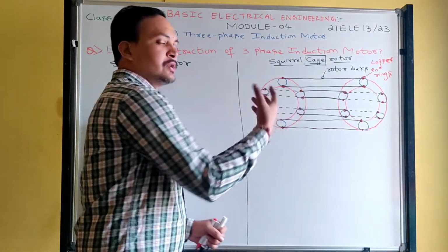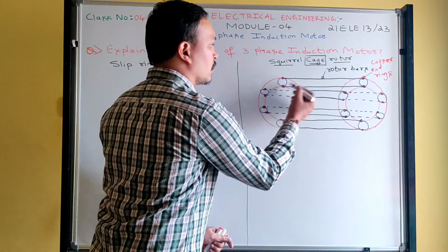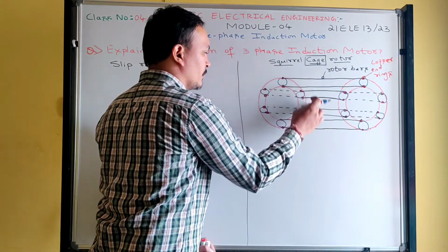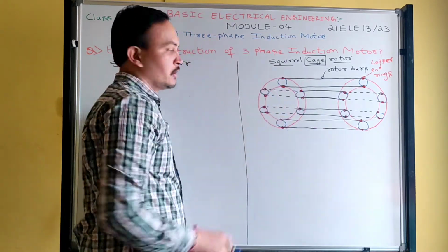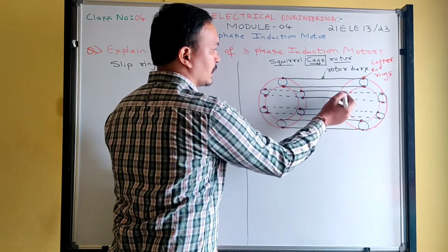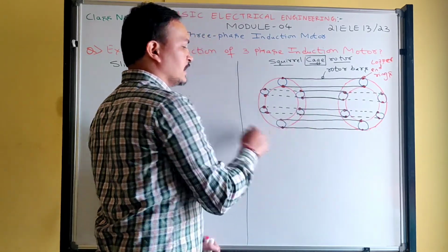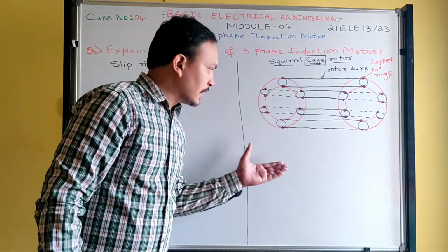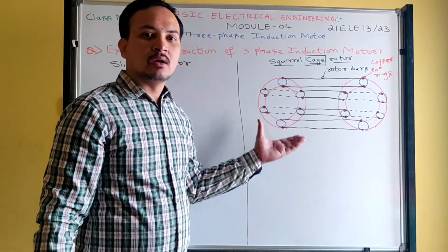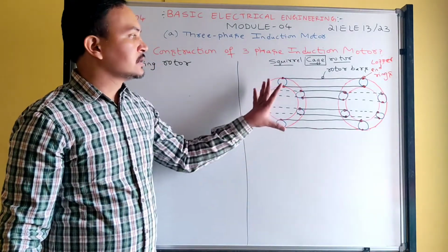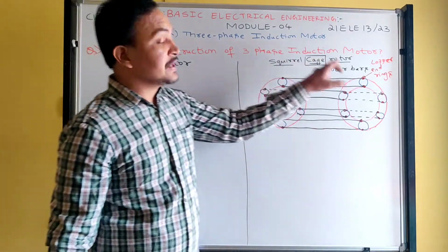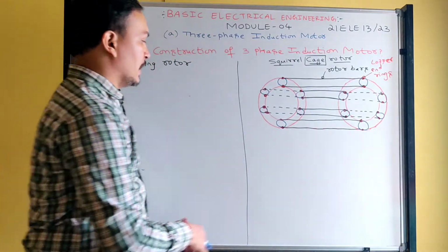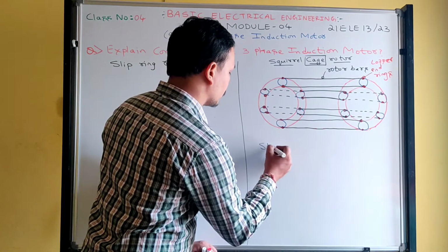See, everything is shorted. See, this is a rotor bar, so it is completely soldered, and this connection will be around rotor laminated plate. Similarly, another rotor bar is connected here, one more rotor bar. Each and everything is completely soldered. Okay, you cannot add extra resistance to the rotor. Okay, because another name for squirrel cage rotor is short circuited rotor. Okay, got it? So another name is short circuited rotor.